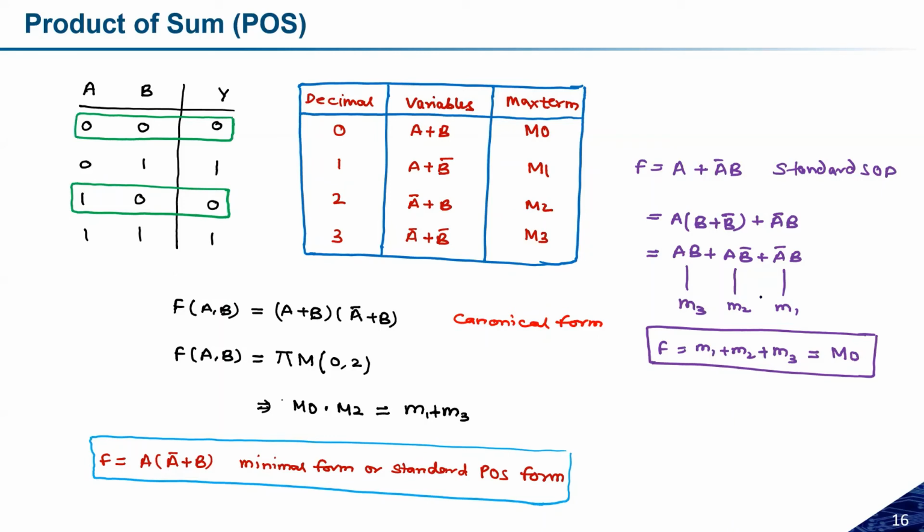If you don't know that you have to convert to another form to minimize the number of gates, you will simply calculate based on the given expression, and that will become the incorrect answer. So first you need to think whether, after converting from one form to another, the number of min terms or max terms is reducing or not. If it is reducing, then you need to convert it.